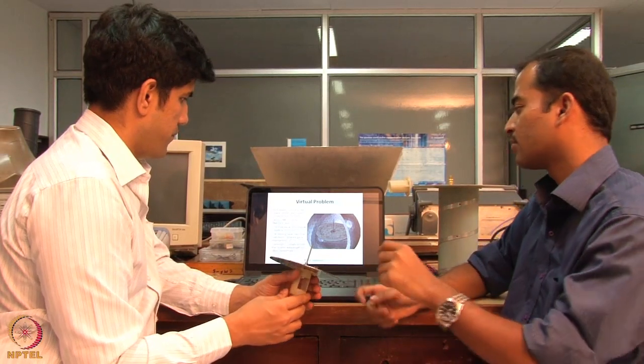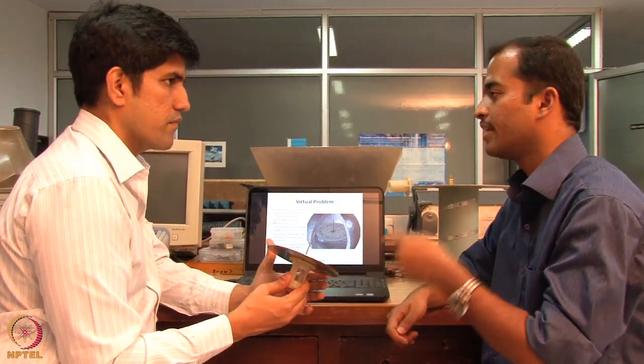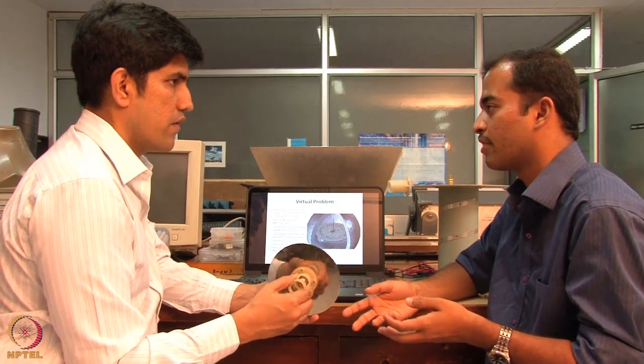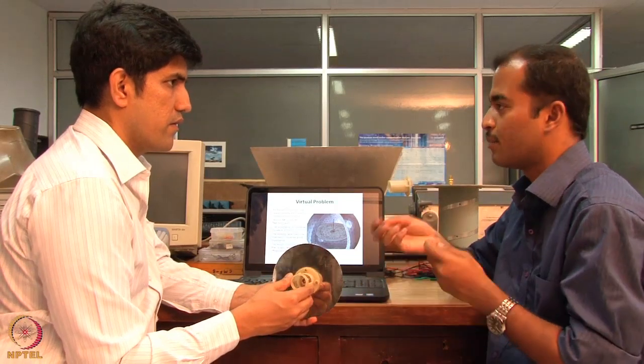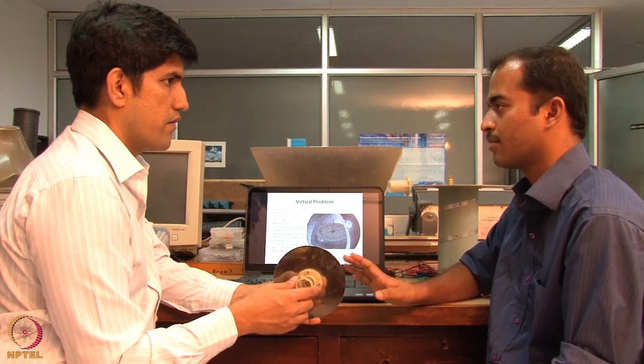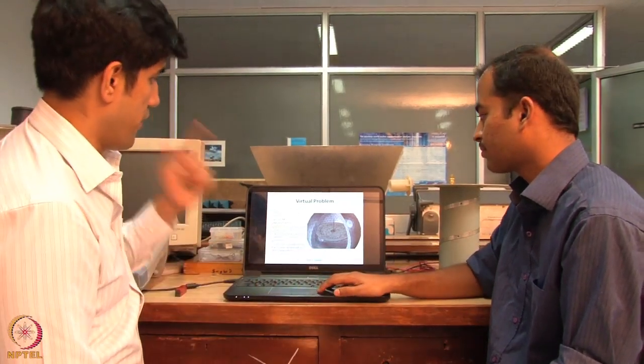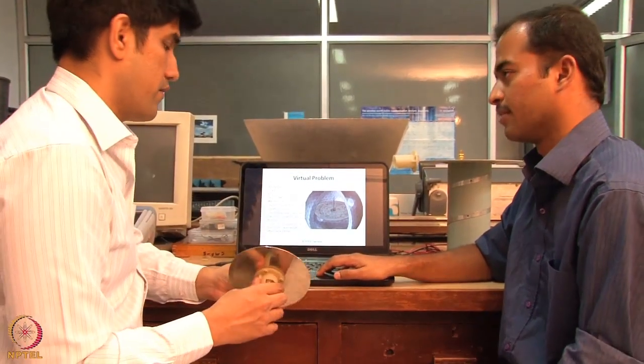So that's what the issue is: the feeding cable which we use, the coaxial cable, has some real impedance, maybe of 50 ohms or 75 ohms. So there is an inherent mismatch, a little mismatch in the antenna itself. The feeding cable is normally in the range of 50 ohms.